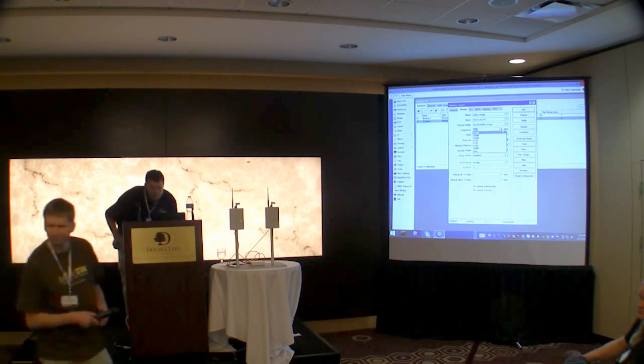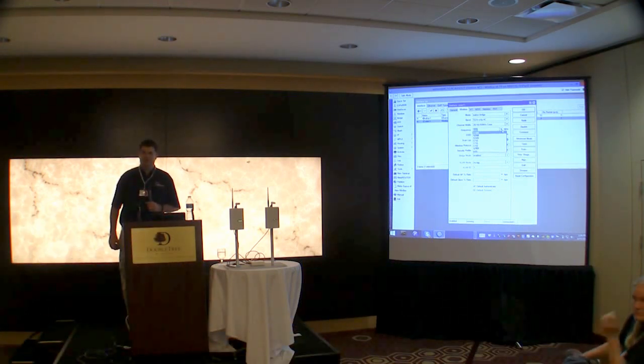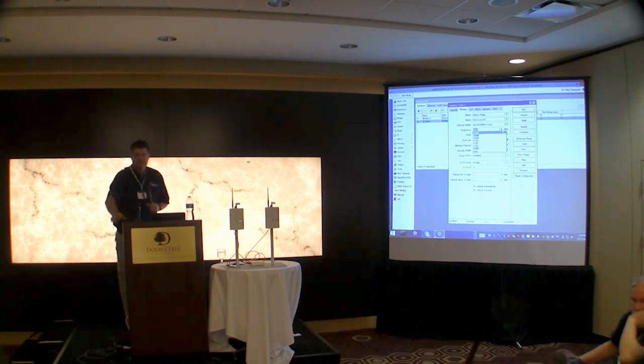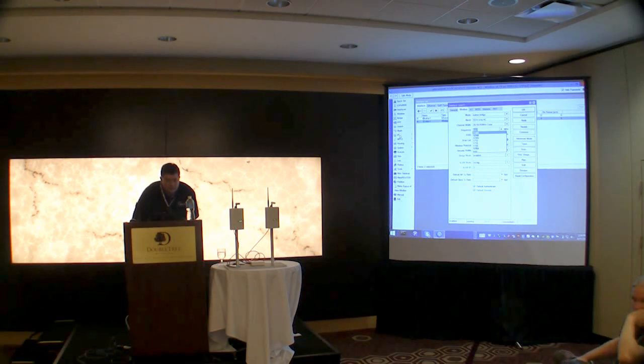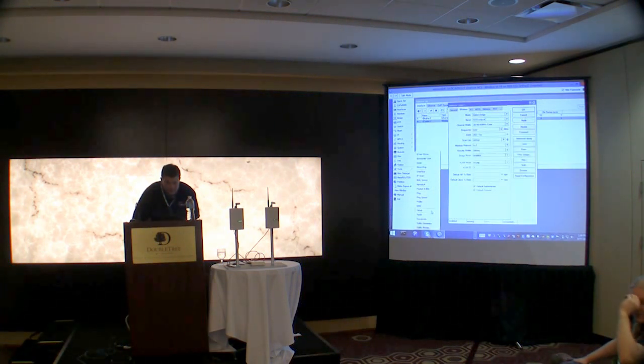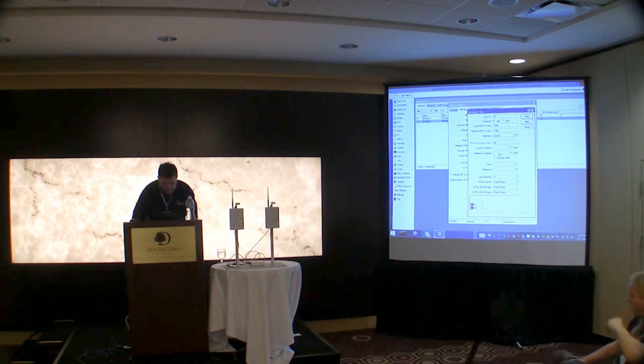I just was going to comment on his comments about GPS synchronization. I know we have several different sites with not MikroTik equipment, with Ubiquiti equipment, back to back. As long as you have good enough RF isolation, you really don't even have to worry about it. I have equipment that's maybe 8 inches apart, and I can run the same frequency and still maintain the signal-to-noise ratio, as well as a noise floor of -103 on the one that we just did, and still use the same frequency back to back, as long as you've got proper RF isolation between the antennas. So it just comes down to proper engineering.